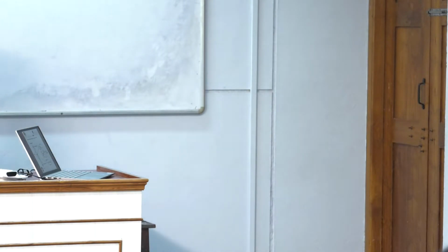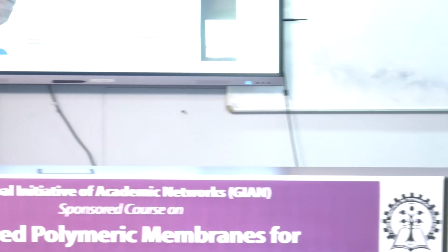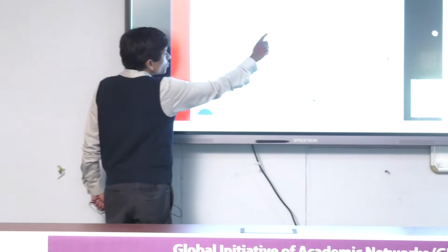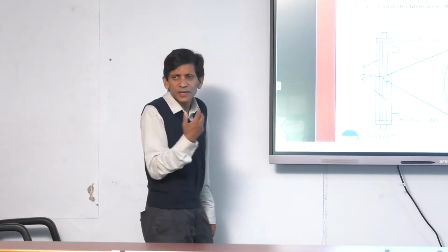It's a hollow fiber, okay? So Asahi only makes hollow fibers. So they are like this, and basically you have a feed port, so the feed comes in here, the retentate comes out here. There are 2 permeate ports, but typically only one is open, you remove the permeate, okay? So this is a very standard hollow fiber module.